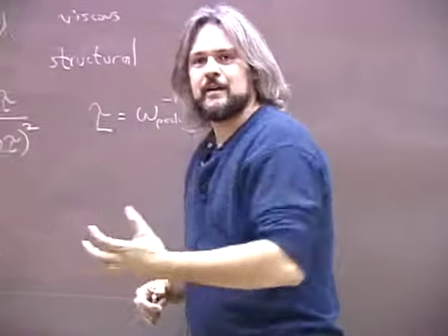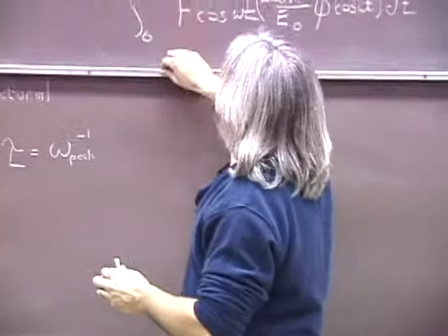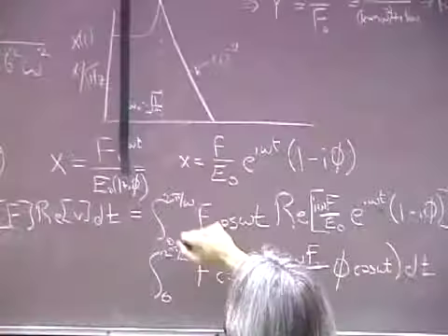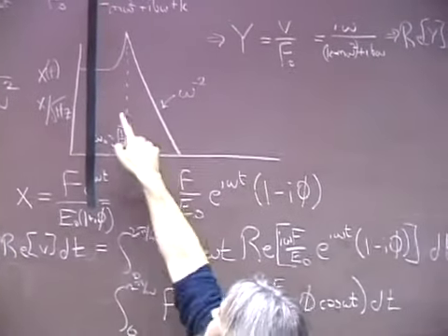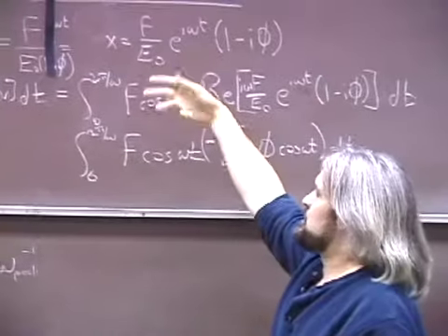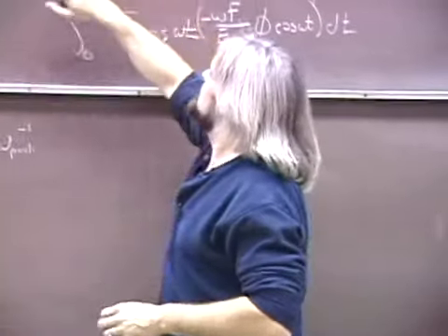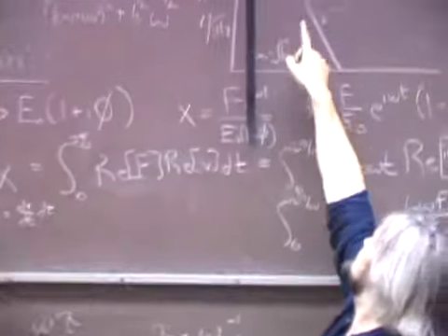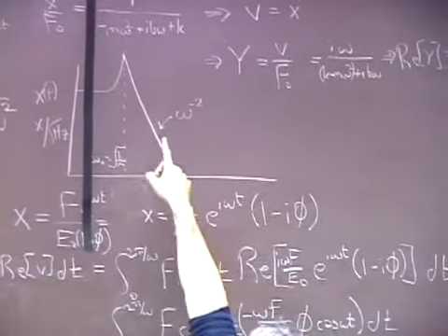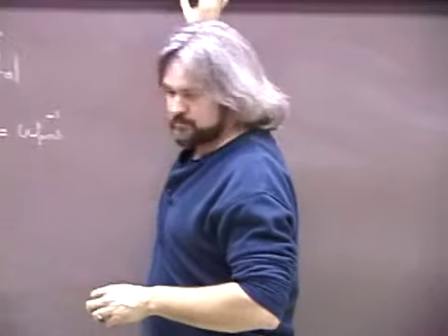For example, if it's a mass hanging from a wire, it's a pendulum, and it's going to want to move a lot at its pendulum frequency. It won't want to move so much here or there. And then this overall mechanical response will be multiplied by some dissipation function phi, and the frequency dependence of this dissipation is going to tell you what the slope of the thermal noise is in the vicinities away from this resonance.